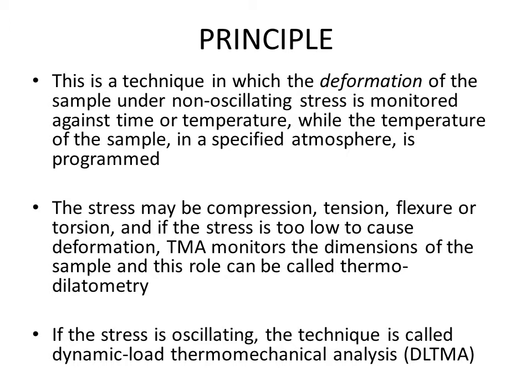Now, the stress may be some sort of compression, or it may be tension on our sample. It might be flexure, some sort of bending, or torsion, some sort of twisting. And if the stress is too low to cause deformation, then in this case TMA monitors the dimensions of the sample, and this role can be called thermodilatometry.